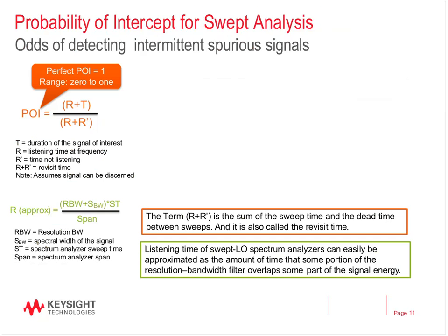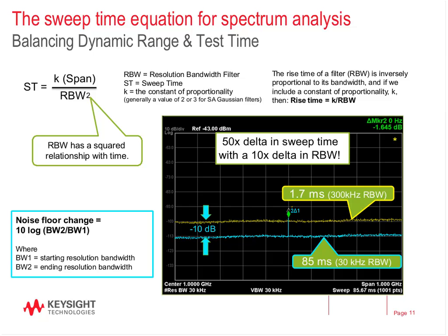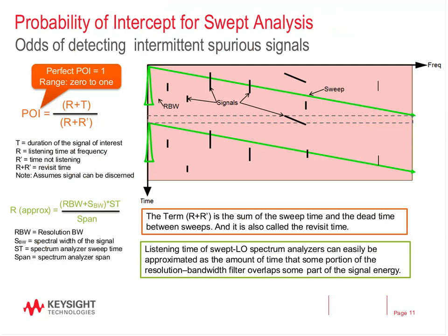Now, the other thing is this is great for continuous wave, CW-like spurs, but maybe your design has some sort of intermittent or walking spur. Maybe there's some fractional-N loop errors or other things causing a walking spur. So how do you trace those down? Well, for a swept-tuned spectrum analyzer, as you're sweeping, and we have the graphic here, your spurs might be showing up periodically.